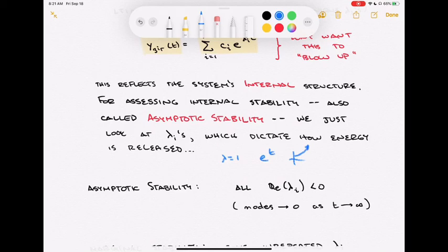We know we'd be in deep trouble. So, some different cases. We said lambda being in the left half plane would be like lambda equaling -1. That would be a mode like this, decaying, right? You could have something like lambda equaling 0. That's e to the 0, that's just a constant. So that's neither growing nor decaying. It's right on that boundary of stability. And we had something like lambda equaling 1, that gave us an e to the t that was growing.